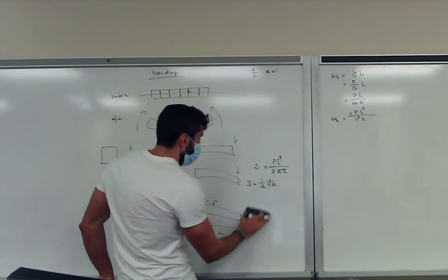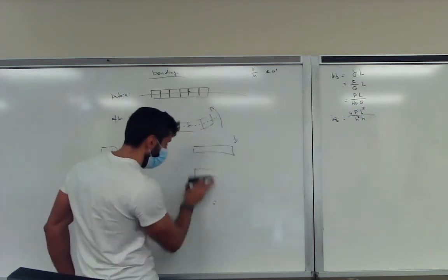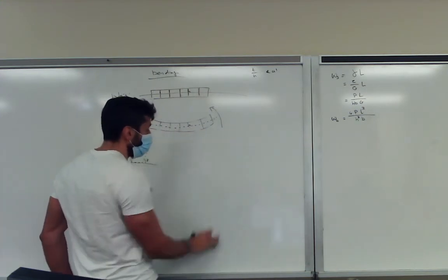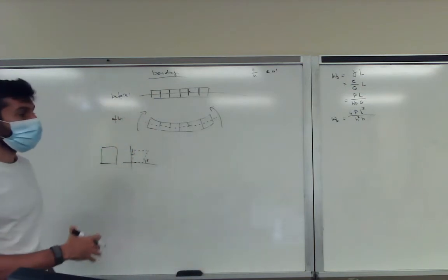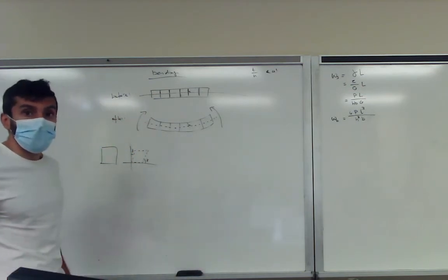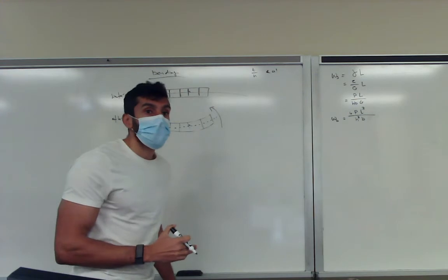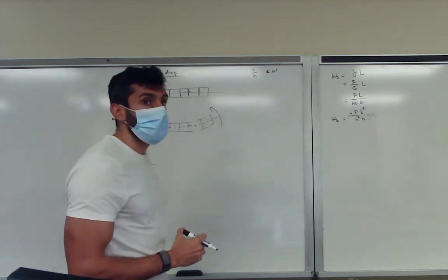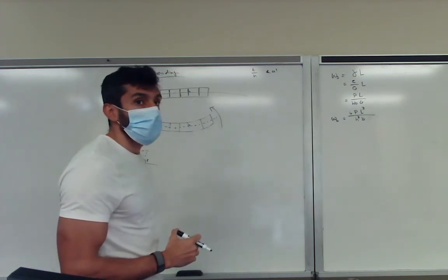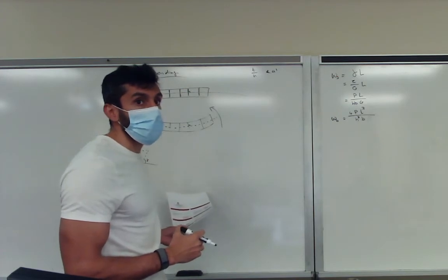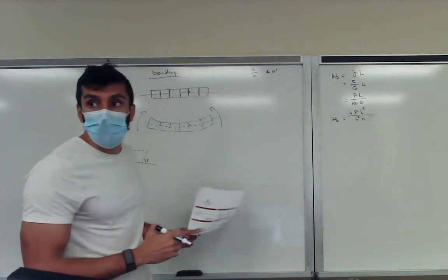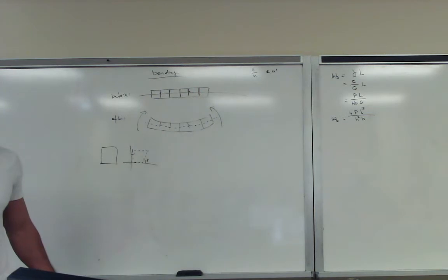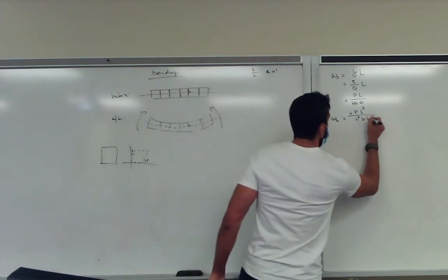So if we do that, we can come up with a formulation that depends on the length, the thickness and the other properties. Yes? So that essentially means we could add the two deflections to end up with the total deflection. Yeah, you can superpose these deflections and get a total deflection. Yes? Where does the Young's modulus go for W_b? Oh, yeah. Like that.